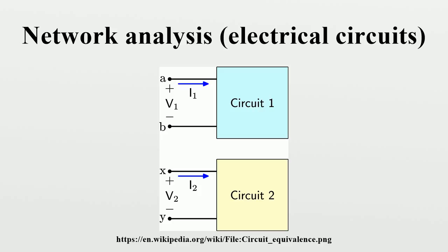Most commonly in electronics, transfer function is defined as the ratio of output voltage to input voltage and given the symbol A, the A standing for attenuation or amplification, depending on context. In general, this will be a complex function of j omega, which can be derived from an analysis of the impedances in the network and their individual transfer functions. Sometimes the analyst is only interested in the magnitude of the gain and not the phase angle.